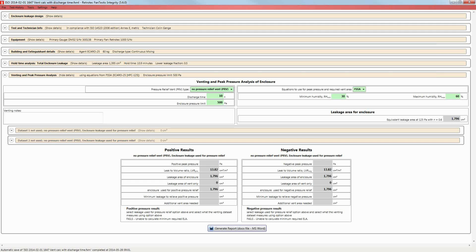So, someone was saying that most air conditioning units are recirculating air on the inside. That is true. If we are doing a test and we have a situation where the dedicated HVAC is going to be running inside the enclosure and blowing air from the room into the subfloor, the pressure in that subfloor will often be 25, 50, 100 pascals or whatever. That has to be entered into the software as a pressure that will be there during the hold time.